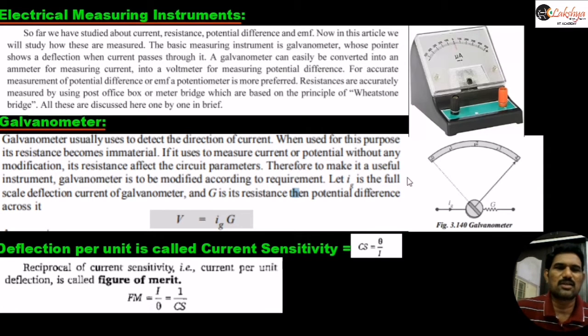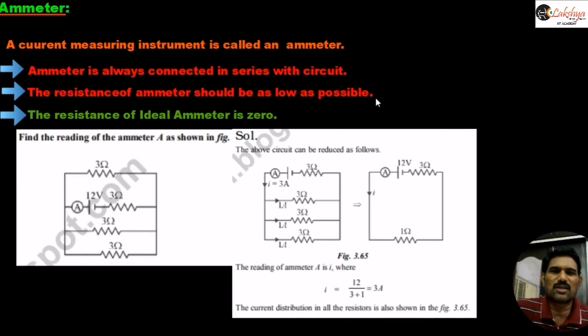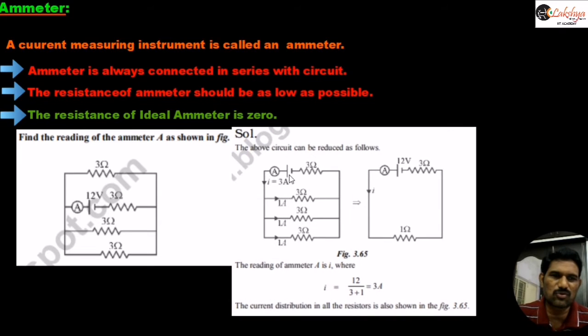And so whereas this ammeter, we can measure any range of current. That means for different ranges we use different types of ammeters having different ranges. Now this ammeter is always connected in series with the circuit. Wherever you are connecting, suppose along a particular path here, for example, if you want to find the current passing through this path here,